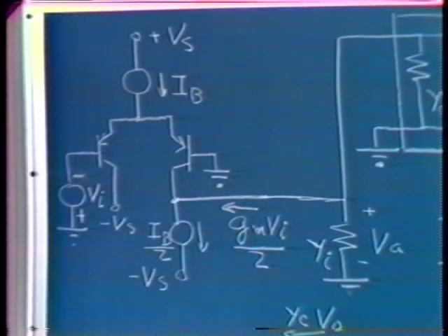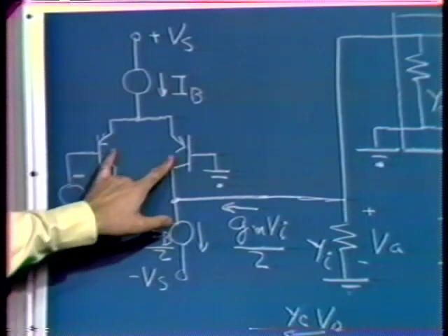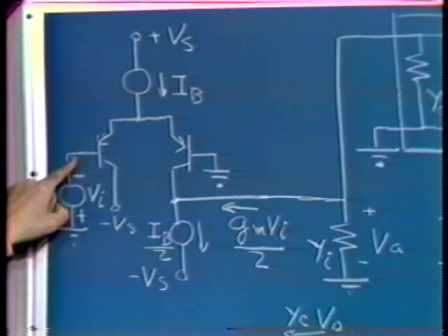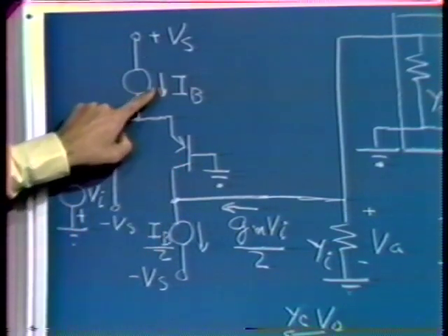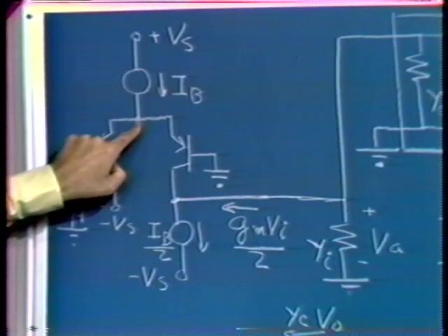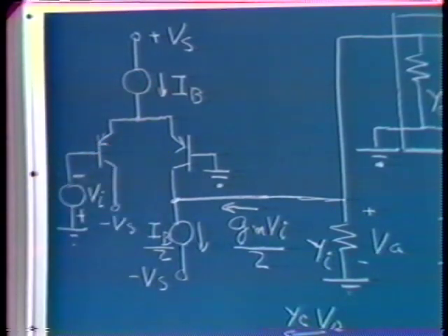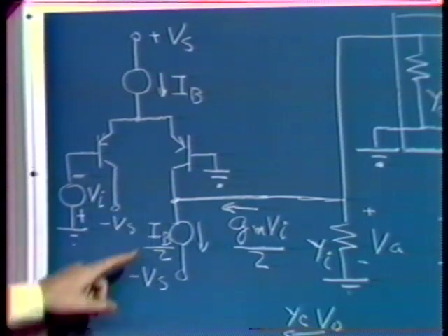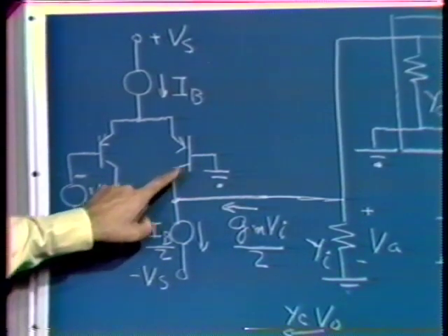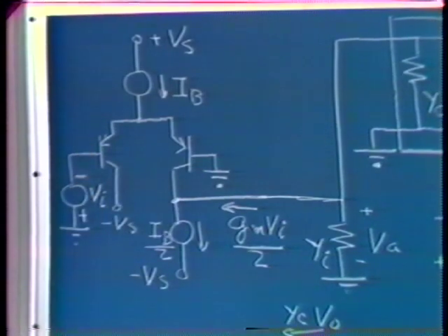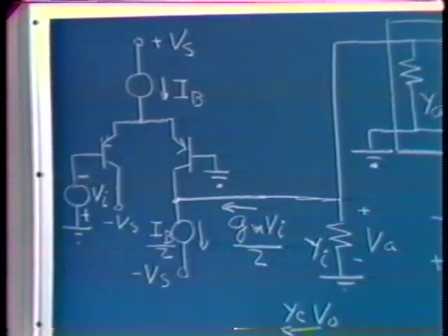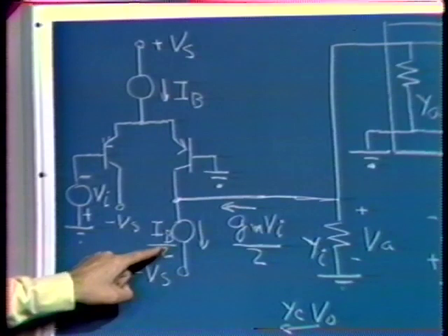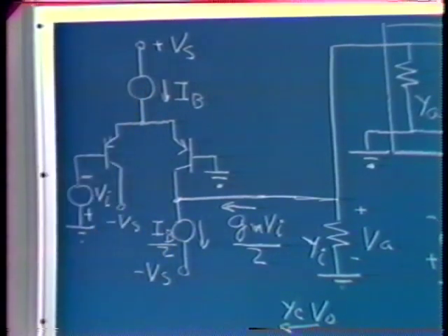The rationale for that, of course, is that if these transistors are well matched, when we have VI equal to 0, the current applied to the emitter of the differential pair would divide equally between the two members of the pair. Consequently, the quiescent collector current of this transistor, with 0 volts applied to the differential pair, would be 1/2 of the bias current.